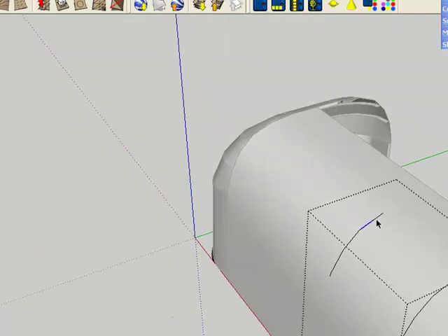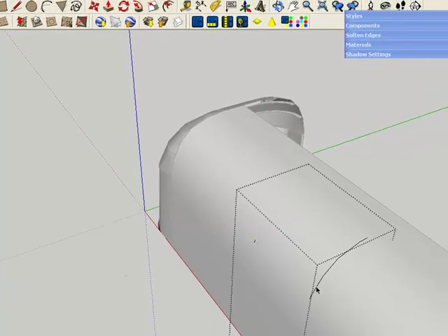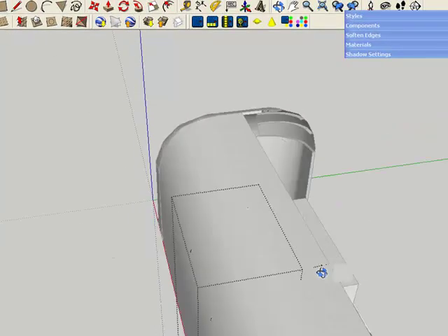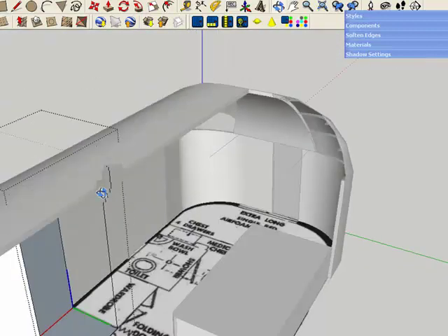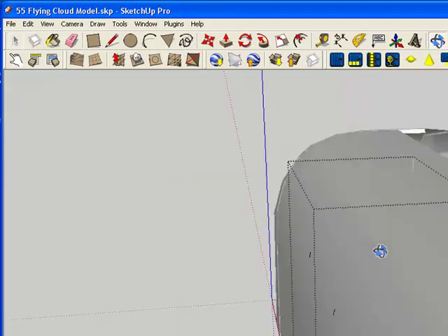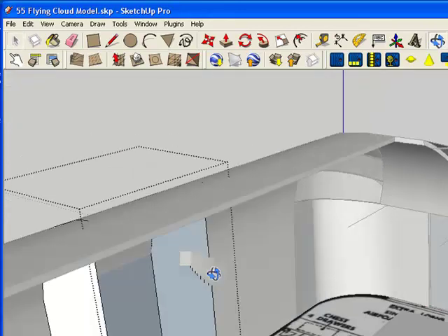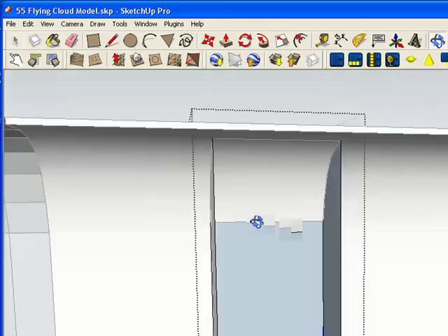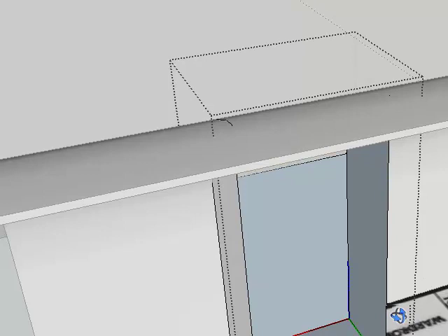And I can even come, because I know I don't need these anymore, and delete the lines that would have been on the outside shell. So I still have the nice clean look of the outside shell. And let's see if I still have my cabinet. Now see, I lost part of it, and the reason is because the intersection here wasn't complete, and that's the kind of thing you have to deal with. So I'm going to use Control-Z and go back and recreate those shapes until, okay, there's the piece I need now. Okay, and there's my cabinet.